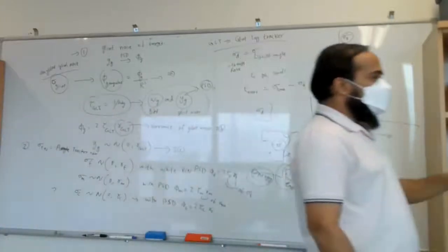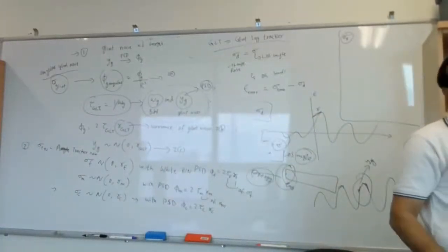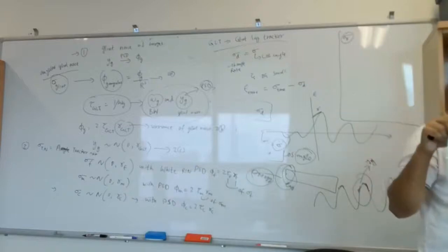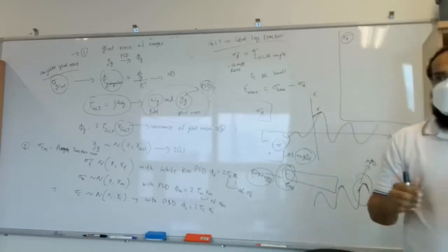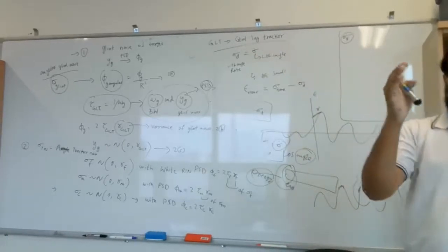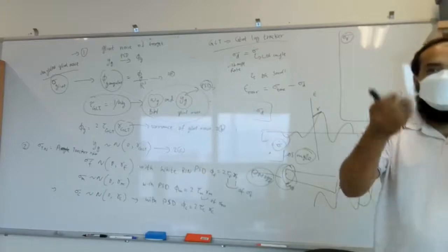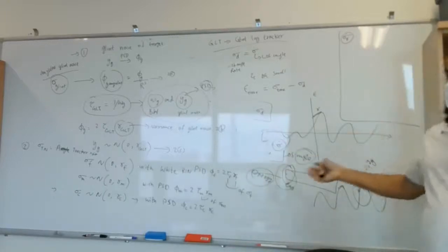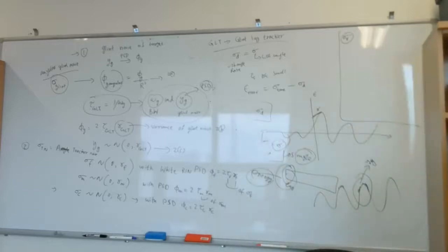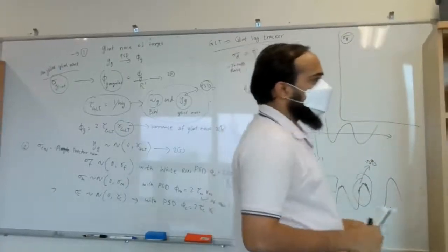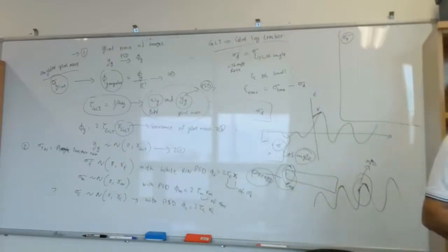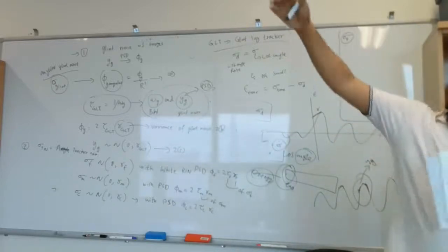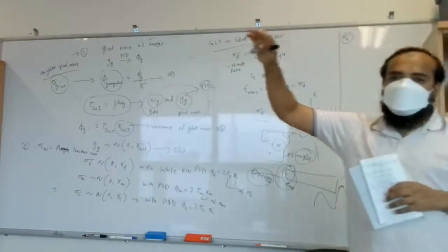So decreasing the range, meaning if the missile and the target are very close, increases the glint noise. If the missile and target are very close, the glint is more; the frequency of the glint increases, but it can decrease the thermal noise or receiver noise. But if the range is far, the glint noise decreases. If the target is far, then the glint noise is very rare, very small.